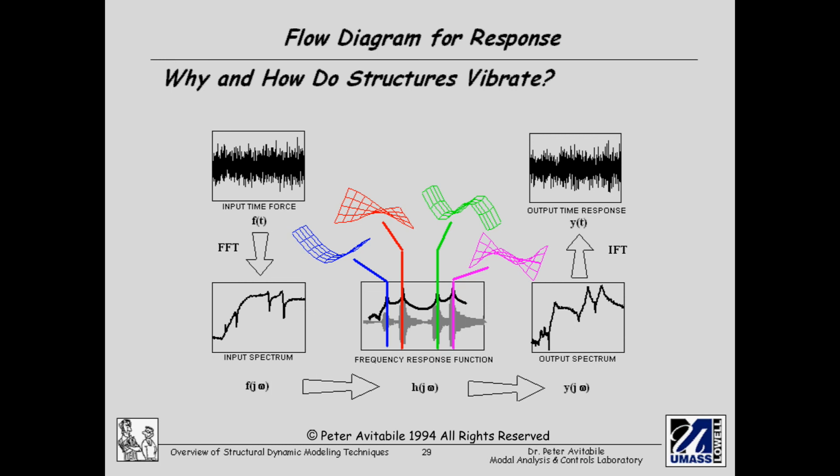So if I look at the energy and I look at the power or frequency spectrum that excites the first mode, I know how much of that time force is going to cause the first mode to respond, and how much of that time force in the frequency domain is going to cause the second mode to respond, and the third mode, and the fourth mode. So the frequency response function becomes a very important parameter for me to understand how the input signal is amplified and attenuated on a frequency basis. This causes this output spectrum.